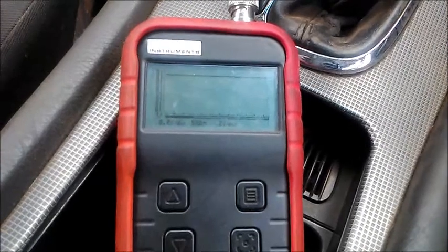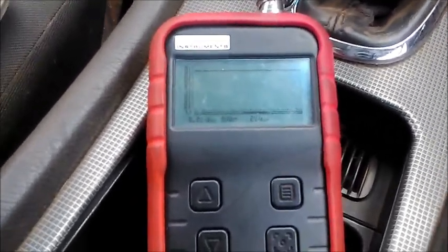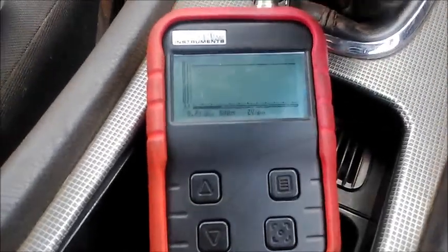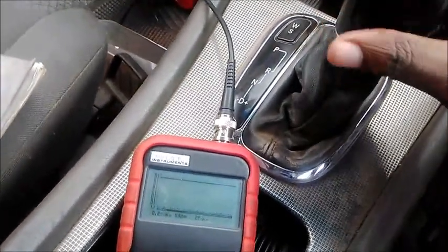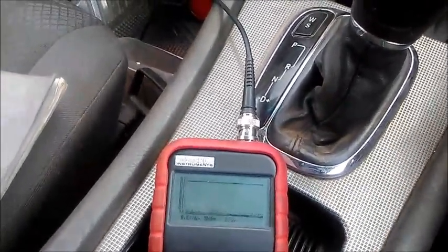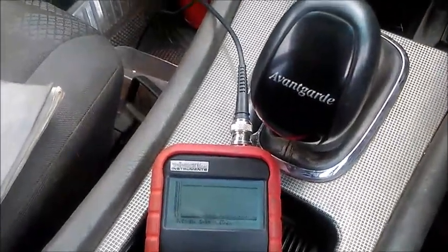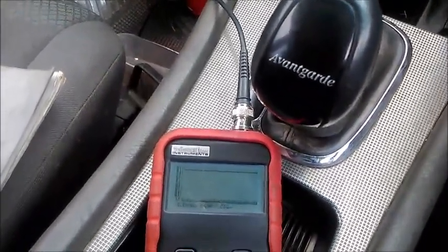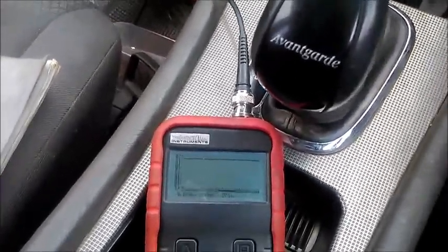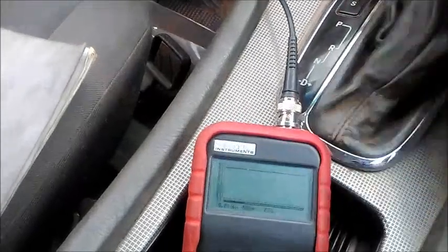Back in R, there is nothing on that line. The voltage remains high all the time. I'm in R now. Reverse a little more. No signal. Put it in D. Move forward. I'm moving forward now. Nothing. The signal remains high.